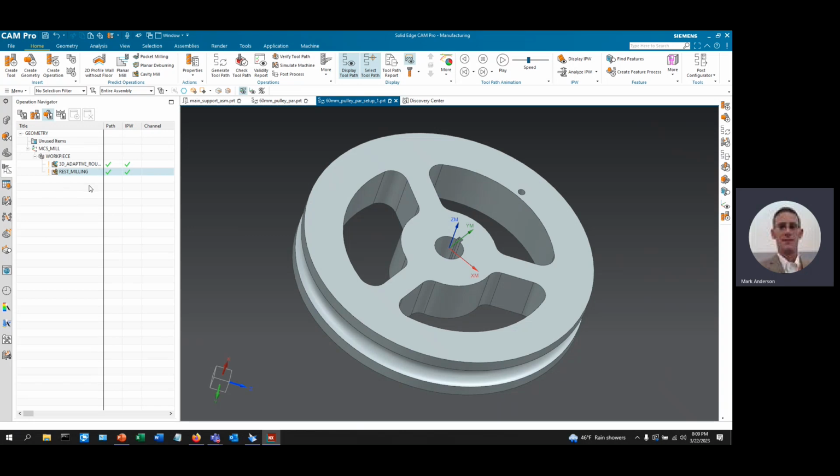So just so you're aware at this time, I'll let you know that the 2.5 axis module is fully capable of doing 2 plus 2.5. So you could put 2 rotational axis. If you had a 5-axis machine, you could use your current Solid Edge package with 2.5 axis milling and do rotations.